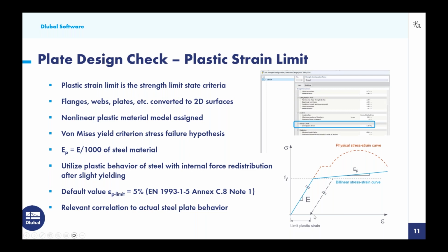So we set this plastic strain limit, again, follow this dotted line up to allow partial yielding. Now the default here is set at 5% for that plastic strain limit. This comes directly from the Eurocode with the section listed here. When we reference the AISC, there is no specific reference to what the plastic strain limit should be set to when we are considering FEA modeling for connection design. So therefore, we do refer to the Eurocode, but this is fully adjustable in the program.